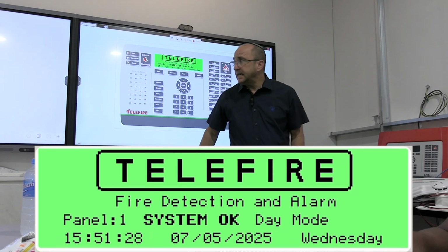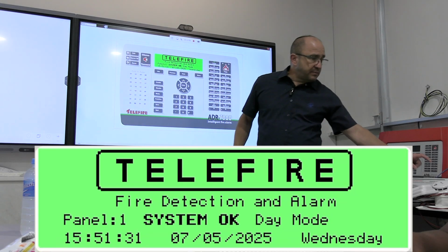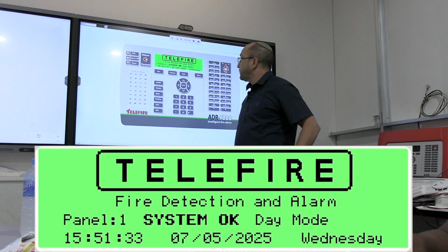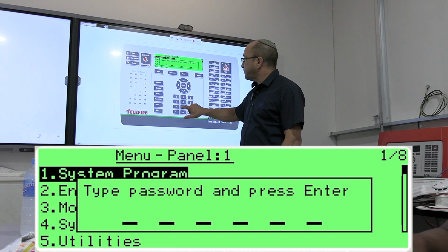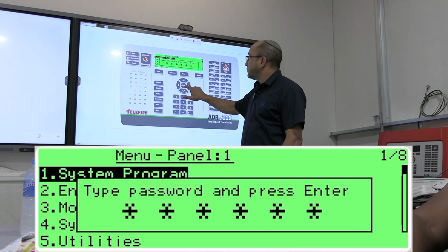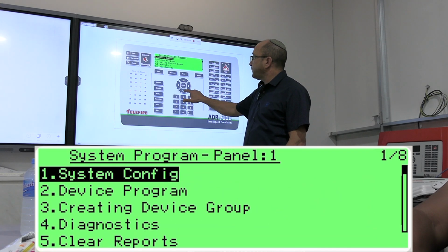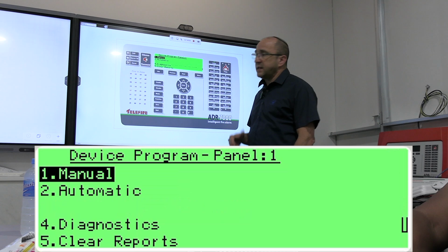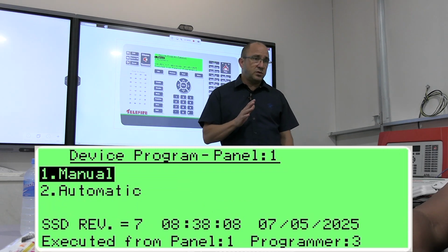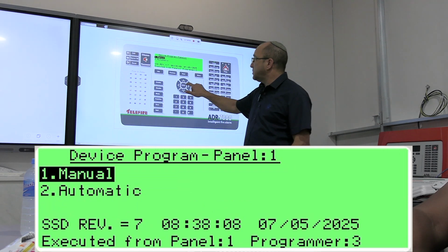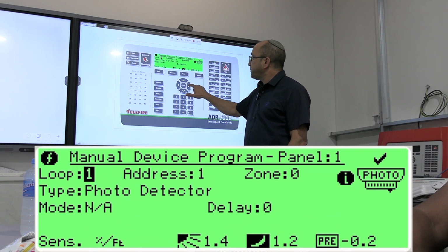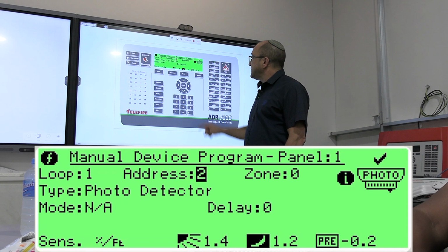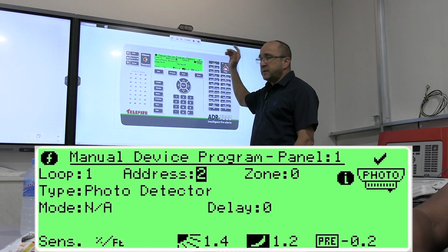Okay? Now I'm reminding you, address number 5 is not programmed. Menu, system, program. Let's start going over. Device program. I can do automatic, but I don't want to do automatic. I would like to see what's going on. Number 1 is a photoelectric. That's true. And you see there's a V, a check. It means that it's active.